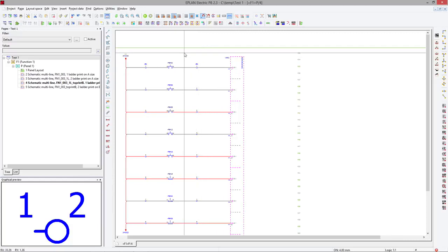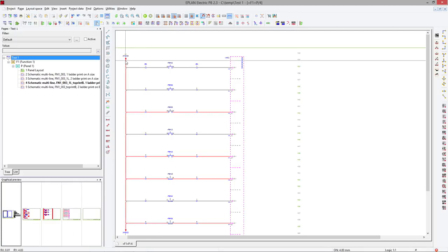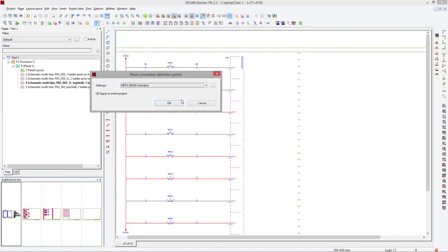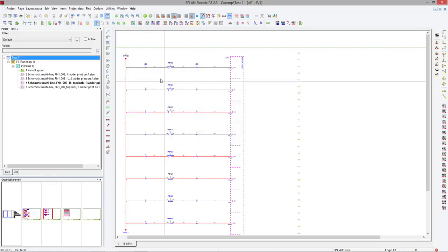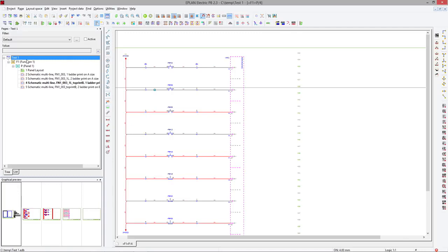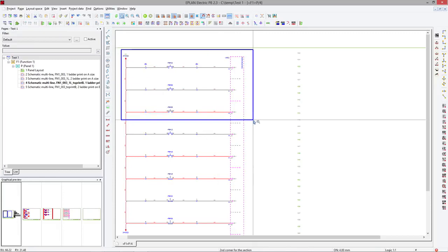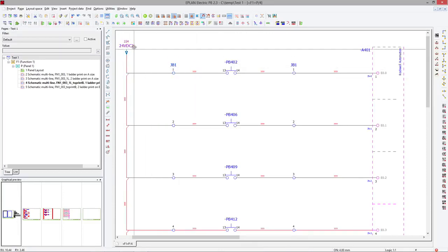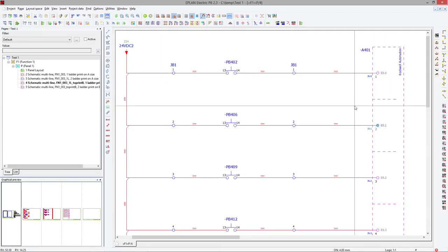Once this is done, fairly easy, you just take the project and you're ready to do the wire numbering. The wire numbering is a two-step process. First step is placing a wire number. When you do place a wire number like this, it basically places a wire tag everywhere where there is a standard wire. Now, another thing we want to do is number these wires. Very often in an environment like this, people will number what's on the left-hand side according to the source, like 224, and on the right-hand side according to the signal, so the I/O address of that particular PLC card.